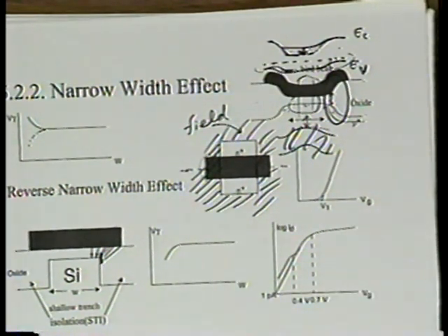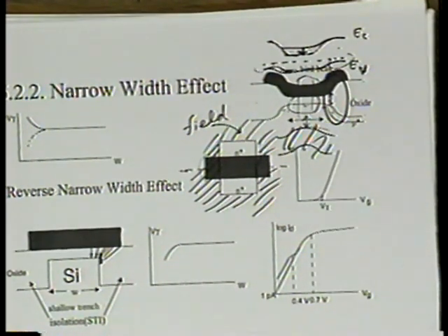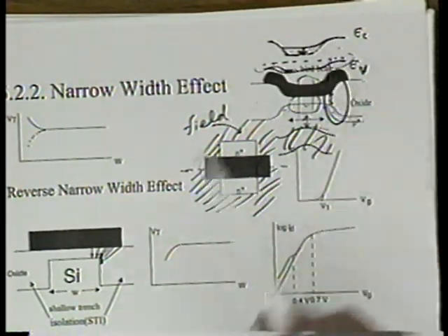Okay, question. How abruptly can one actually change the doping like that? I'm asking you to visualize that you can change the doping absolutely abruptly, as abrupt as you want. In other words, there are two questions involved here, and I want to force you to think about the physics, don't think about the technology. Technology-wise, of course, there's always the Gaussian profile, and I know you all know that. But even if we have an absolutely abrupt transition of the doping from heavily doped P to lightly doped N, I want you to understand that the heavily doped region still has influence on this energy band shape.